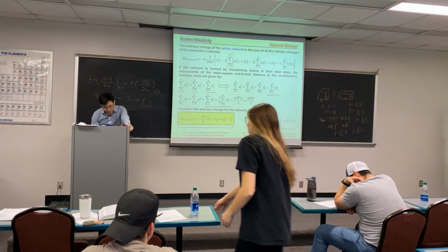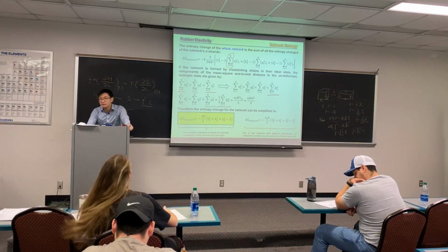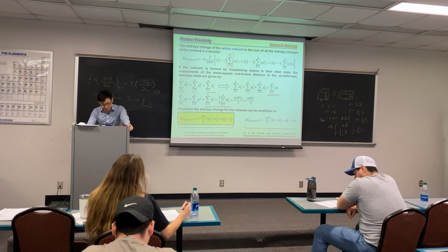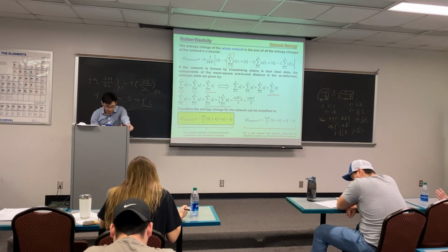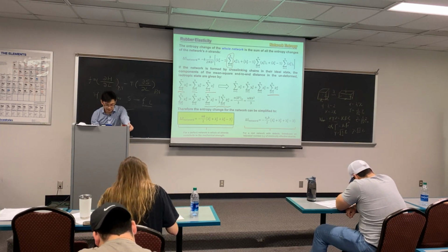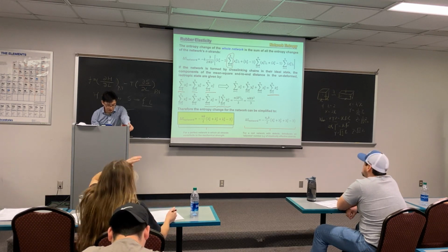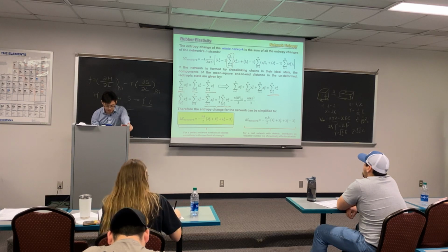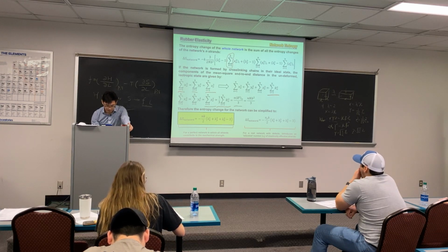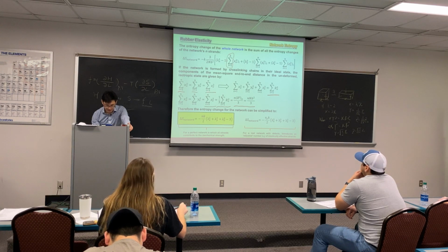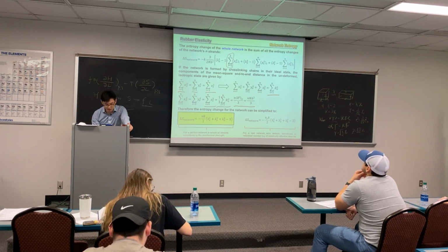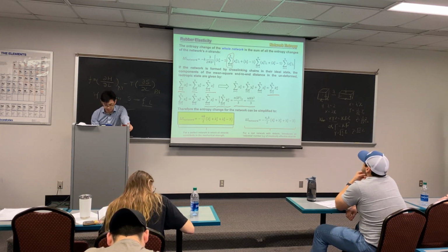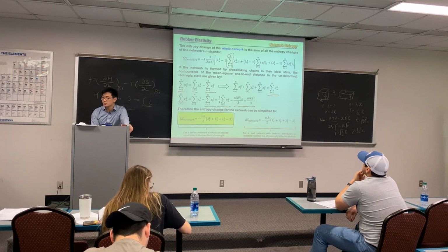So how can we further simplify this? R0 square, and we know R0 square will always be the same. And we know it needs to add up n times, or there are n strands in the system. So this will equal n, the number of strands in your polymer network, multiplied by R0 square, the initial end-to-end distance, divided by 3.